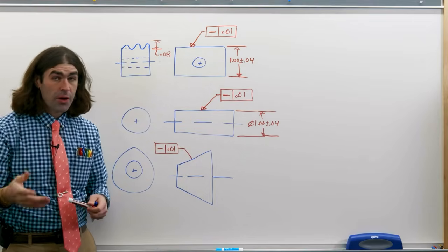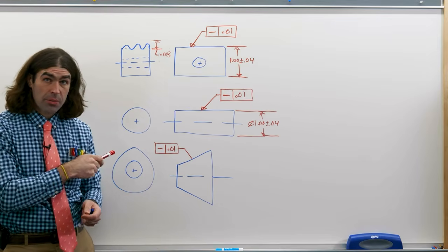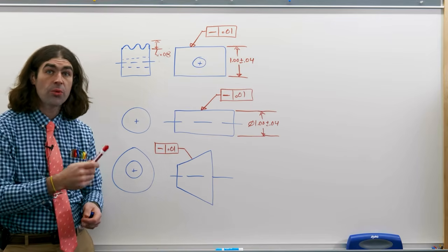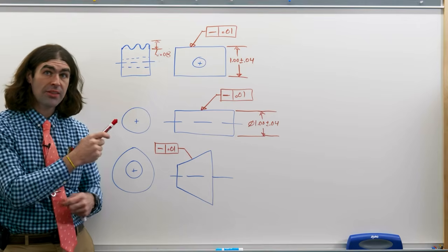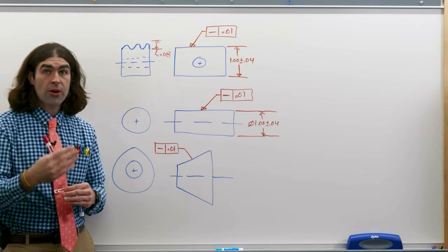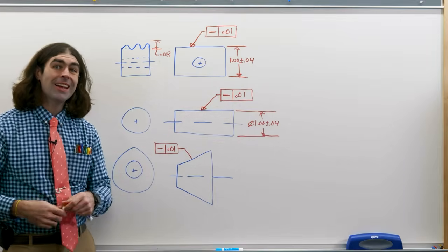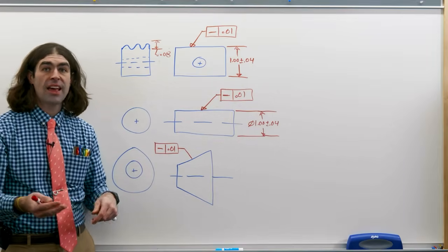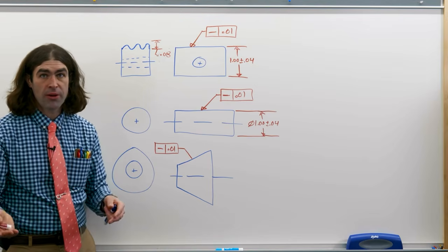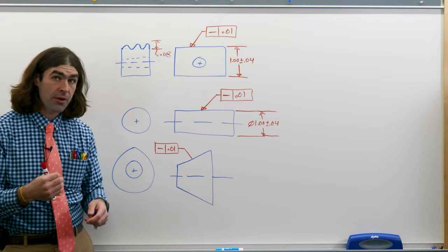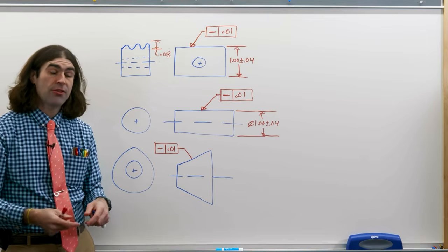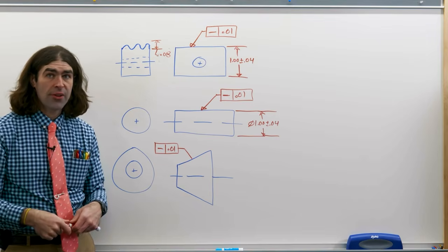Now, rule number 1 applies when it's applied to surface entities like this, so that 10 thousandths straightness tolerance can't be any larger than the MMC. The MMC of this part is 1.04. You can't add the straightness to that to say, oh, it's 1.05, right? It's still got to be under the MMC, and then you have to achieve that straightness tolerance.